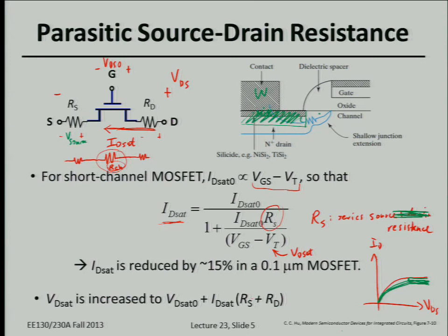We could. All right. So it turns out that if you do that, you start to see significant leakage current. Actually, I'll just say it's from the drain p-n junction. Do you remember what happens in a p-n junction if you bring the metal contact too close to the metallurgical junction? What do we call that when the quasi-neutral region is really short? Short base? A short base diode? Okay, so what happens with a short base diode? And what happens to the current? The reverse leakage current, right?